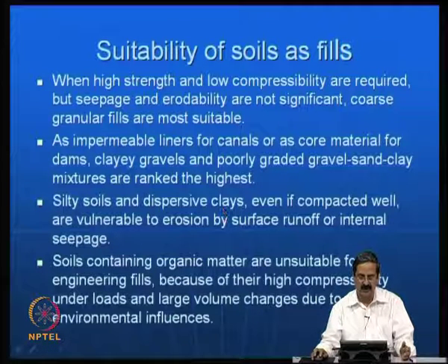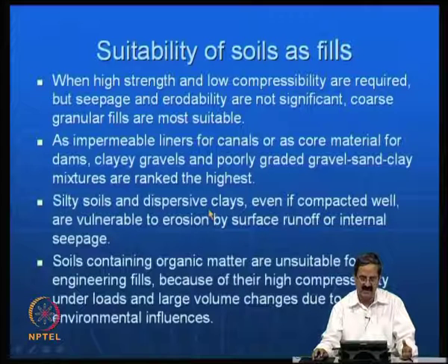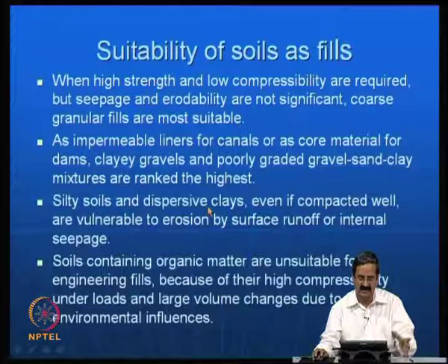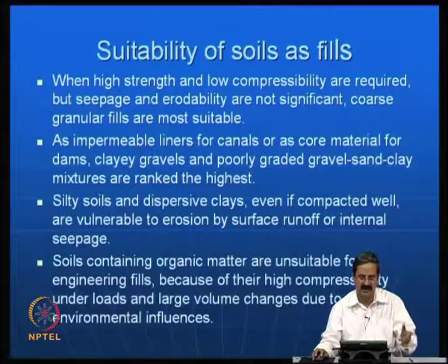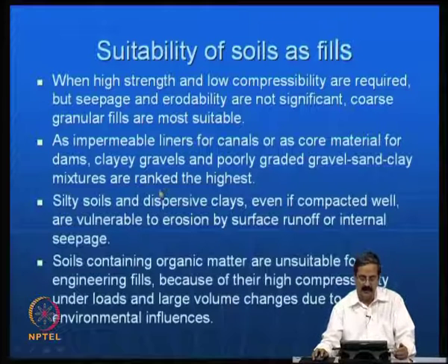It may be very good when it is in dry condition, but when there is surface runoff or water contact, the problem is that it loses strength rapidly and is vulnerable to erosion by surface runoff or internal seepage. For example, if you construct a dam with this sort of silty soil material, there will be cavity formations. As I was just mentioning in the other class, the clay disperses very fast, the particle to particle interaction is not there. So, in the presence of water it tries to move out. So, the problem is that if you have this sort of soils, it is a risky thing.